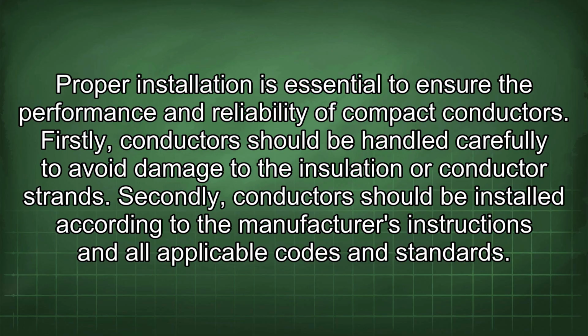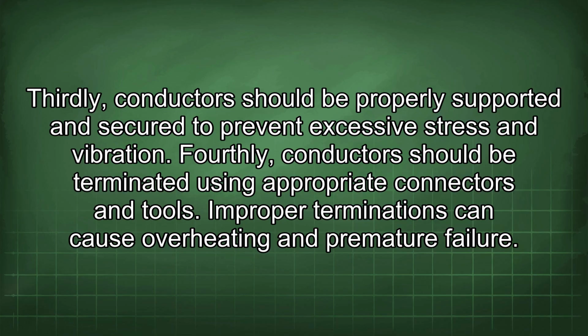Proper installation is essential to ensure the performance and reliability of compact conductors. Firstly, conductors should be handled carefully to avoid damage to the insulation or conductor strands. Secondly, conductors should be installed according to the manufacturer's instructions and all applicable codes and standards. Thirdly, conductors should be properly supported and secured to prevent excessive stress and vibration.